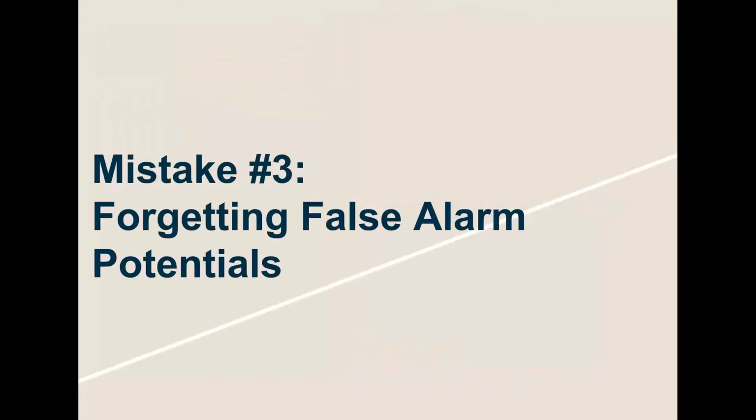All right, so let's jump up to the next one. I mean, the worst thing that happens is you put one of these systems in, and then you get the call in a couple of months where they said, "Hey, the operator shut down the alarm system because in their mind it was putting out false alarms, or the flame detector's going off. I can't find any proof that it should be, so I'm shutting it off or disconnecting it." So false alarms are like the bane of our existence for these sorts of things because they really desensitize people to something when it really could occur.